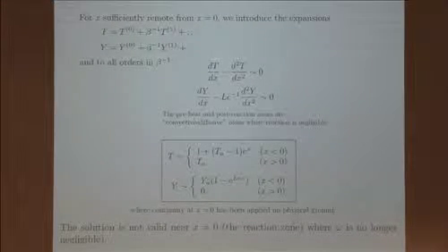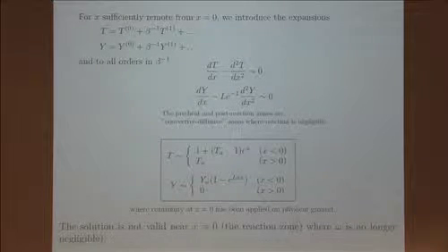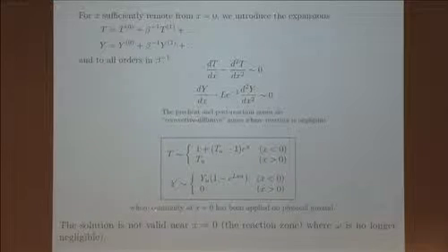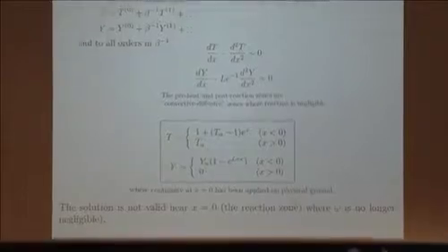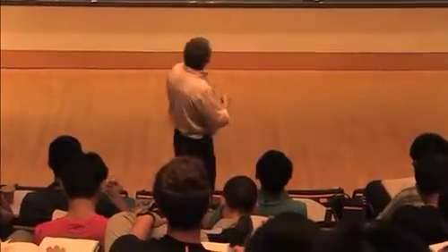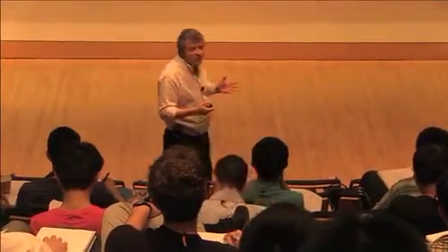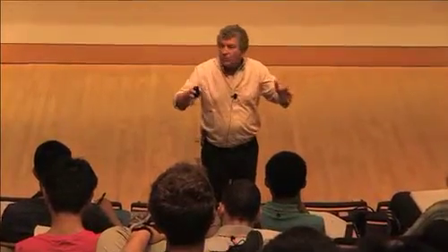The main one that we need is the leading term, and it's written here, where I have assumed already that the temperature and the mass fraction are continuous at the reaction zone, something that you anticipate or expect on physical grounds. Furthermore, we have assumed, without loss of generality, that the reaction zone is at x equal to 0.